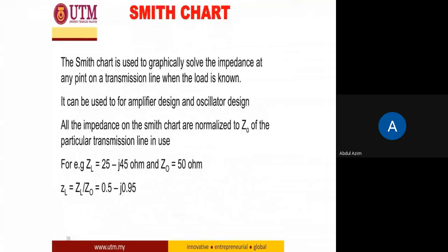So normally to analyze the S parameter, we use what we call the Smith chart. I hope you are already familiar with this. So why do you want to use the Smith chart? We want to match the circuit. In the Smith chart, the middle part is where the matching is done. So basically in this design, we will design amplifier and oscillator design for matching. Filter also we will use it for matching.